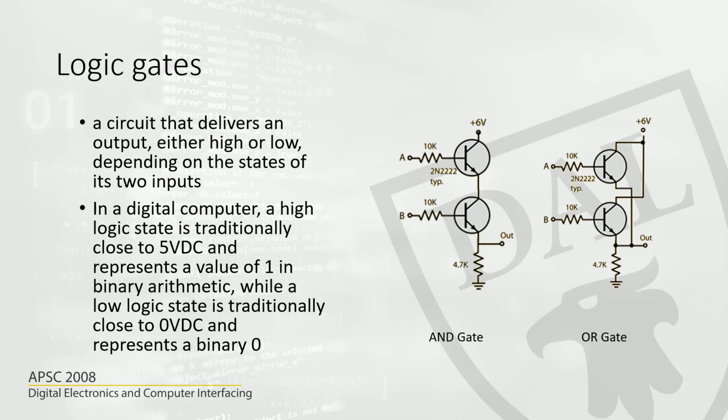Often the ICs we use accept a 5 volt input or say 3.3 volt input. In Arduino, when we say high and low, high is 5 volts and low is something around 0 volts. That's how we say zeros and ones, and that is how we apply 0 and 1 to these inputs and see what kind of output we get.